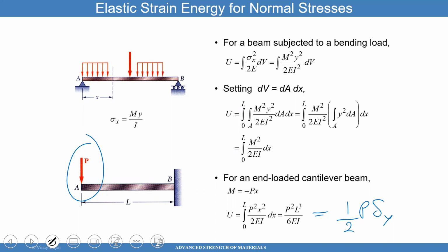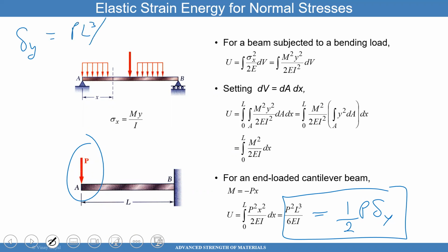Yes? So if I want to find the deflection, don't I have to equate this to that and I'm done? You can equate the work done to the strain energy. And guess what happened? I can calculate the deflection there. What is the deflection? Just do it yourself. You're going to see it's going to be PL cubed over 3EI. Beautiful.